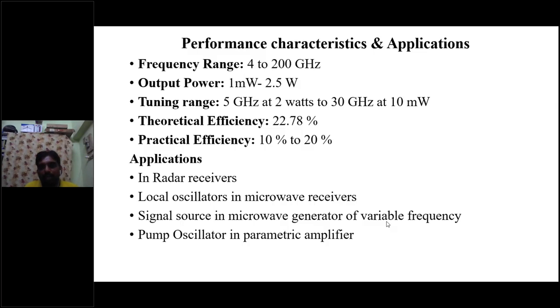The radio frequency input is taken from the reflex Klystron oscillator and transmitted to the microwave bench setup through some components. At the output side, after the slotted section, we connect different types of waveguide components or multi-port junctions, and we can find out their parameters. That is why it is used as a signal source, the input source, for microwave lab experiments.